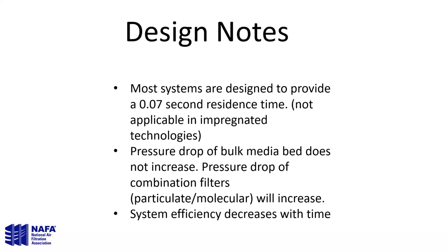It doesn't work that way in impregnated technologies because they actually use fine powder. And as I explained with activated carbon, it's a surface phenomenon. So the more surface you expose, the faster a contaminant can be picked up. But don't confuse that with capacity, because a pound of powder and a pound of granular can pick up the exact same amount. So the powder will pick it up a lot faster than the granular will, but it will not last any longer. And there are benefits to both technologies, provided they're used correctly.